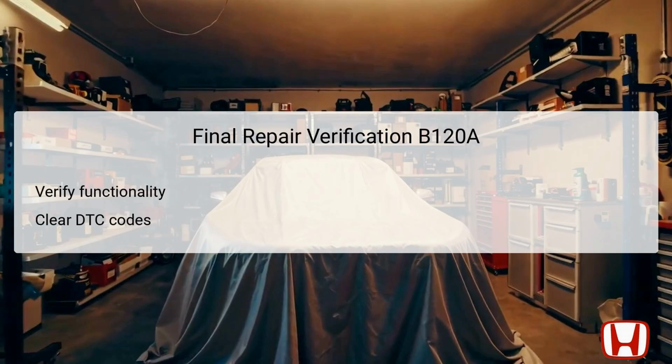After confirming that all functions respond as intended, the next step involves clearing the DTC codes from the vehicle's onboard computer using an appropriate diagnostic tool, such as the Honda Diagnostic System, HDS. Clearing the codes resets the system, allowing for a fresh start for the vehicle's diagnostics. Subsequently, a test drive may be necessary to confirm that no new DTCs appear during operation. Following these steps ensures repairs are effective and that the underlying issues are fully addressed, allowing for vehicle reliability and comfort to be restored.